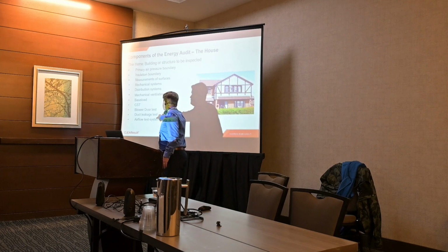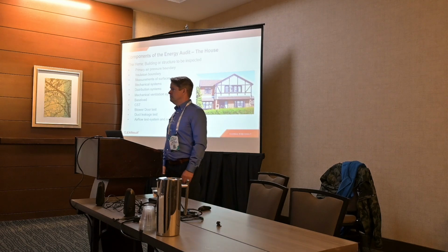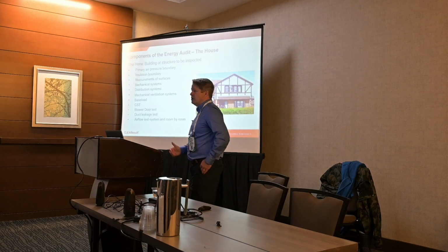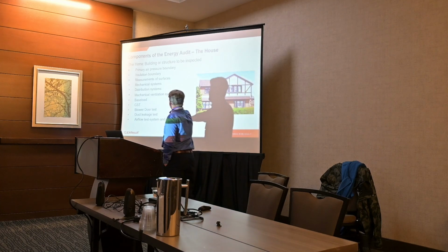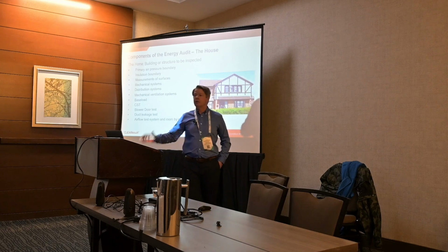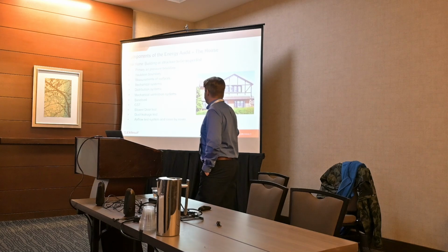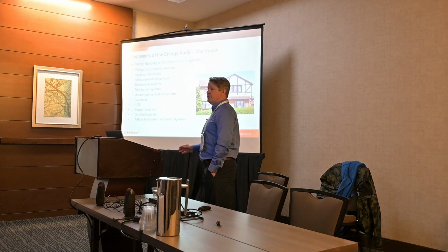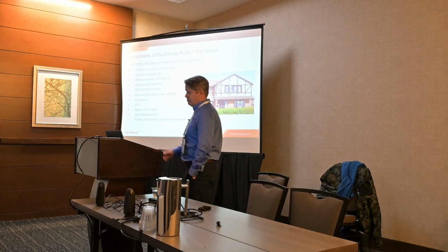Who here does duct leakage tests on a regular basis? No one, right? Once in a while? Yeah. Who here knows how to do one? Oh, good. That's good. Because you're going to need to do one. And then airflow testing also. We need to know how much air is flowing through this whole system, right? So we can make sure that we have the overall airflow that we need. But we also need to know on a room-by-room basis how much air is coming out of each supply so we can see whether or not we can send enough heated air to that space to condition it.